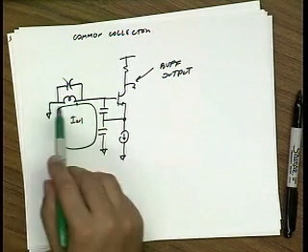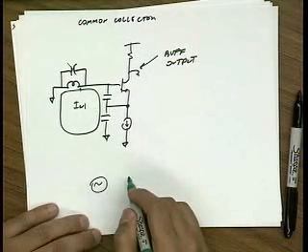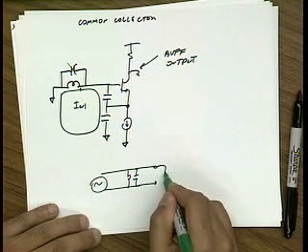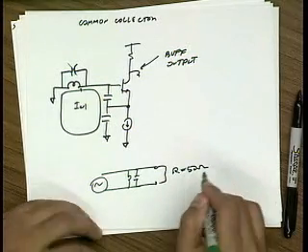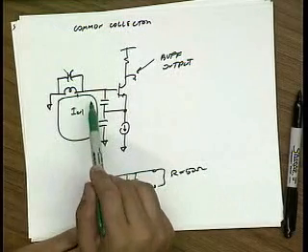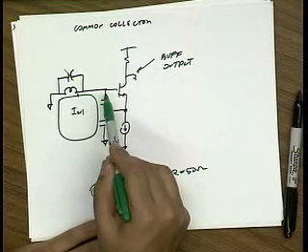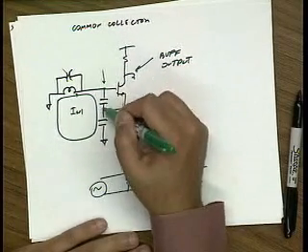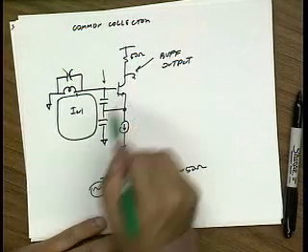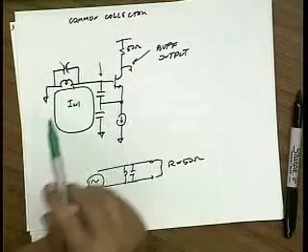So remember, you always need a buffer. If I have an oscillator, let me represent it as an LC tank, I can't just stick a resistor here, let's say 50 ohms, because that'll de-Q the tank. If this is driving a transmission line, I can't put the transmission line load here because that would stick 50 ohms onto my tank. But I can put a 50 ohm load here, and as long as this voltage swing's not too big, it's not going to fundamentally change the performance of this.